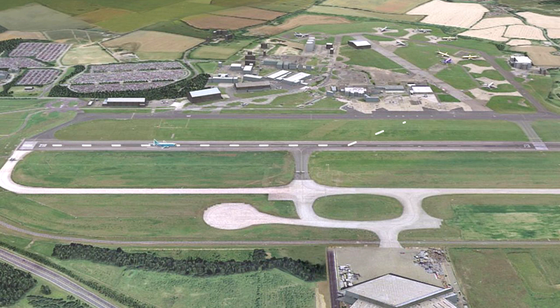The speed Vmu is defined as the minimum unstick speed. Vmu is the slowest calibrated airspeed at which the aeroplane can safely lift off the ground and continue the takeoff. However, despite Vmu being the lowest speed the aeroplane can safely lift off the runway, in actual operating conditions, the aeroplane does not lift off at this speed. The aeroplane is flown so that it actually lifts off at a slightly faster speed.